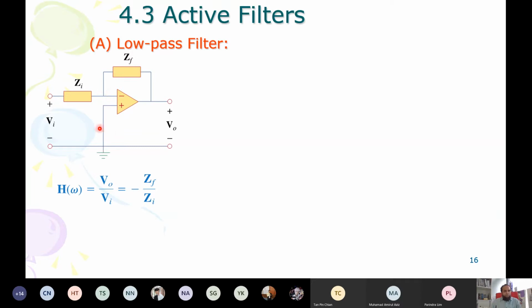So if suppose there is a voltage source Vi equal to 10 volts, it will be 10 here, then 10 here as well. So this gives a hint that we can find the voltage at this node, which is equal to this node, which is equal to 0 in this case. We know for sure for a practical or ideal amplifier, there is no current going in this branch or this branch. So all the current which is coming here is going here.